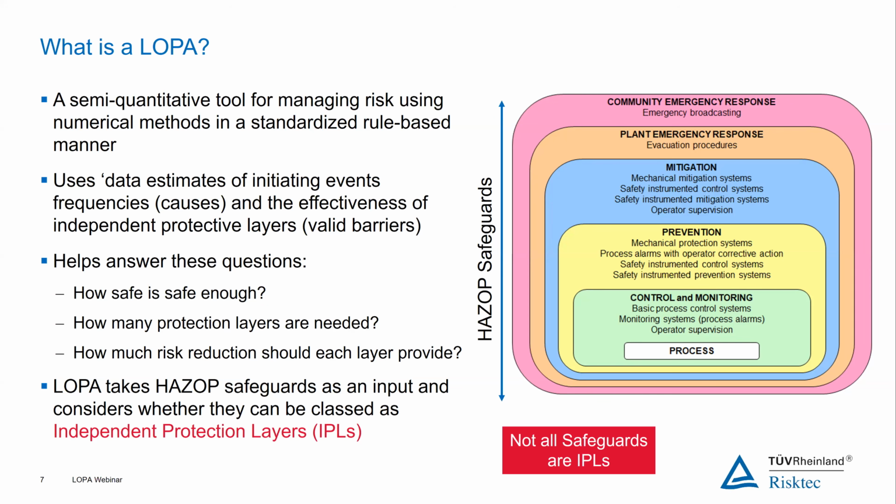Sometimes going into a little bit more detail, maybe 5 or 2.5 times 10 to the -4. Whereas a complex LOPA will inherently use more detailed data and will also maybe incorporate additional considerations into these calculations. We call these conditional modifiers within the LOPA methodology.